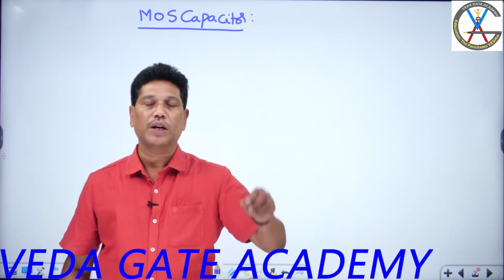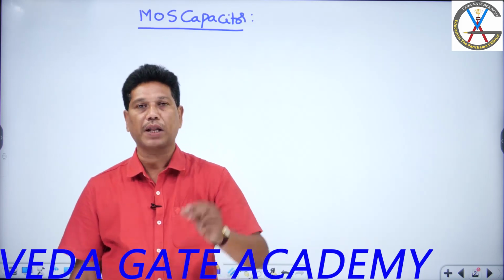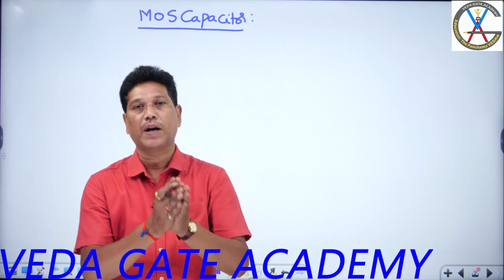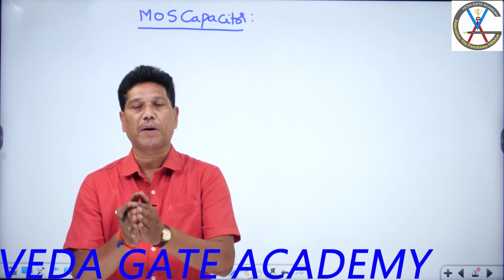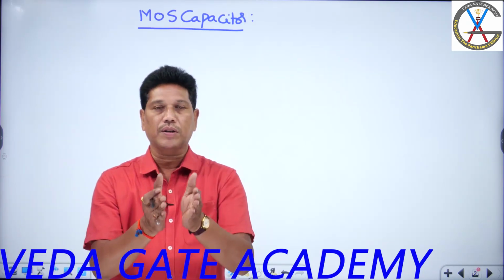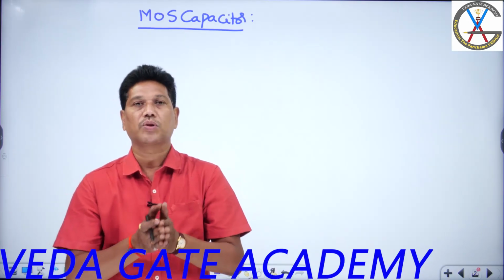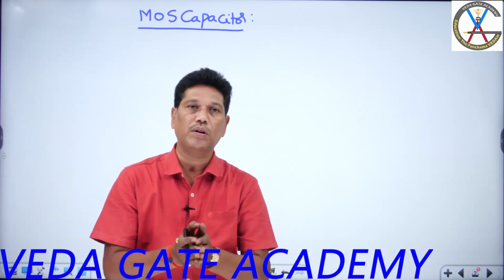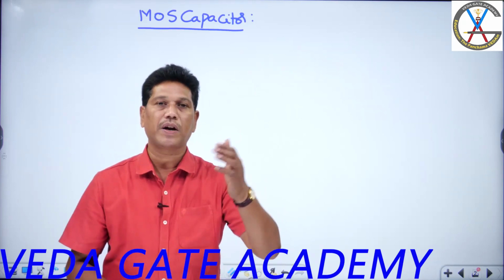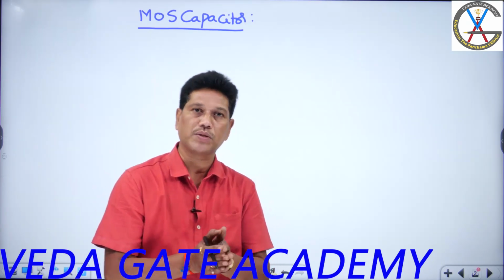And the capacitance of that MOS capacitor can be varied by the applied gate voltage, students. Based on that, this MOSFET is also called a voltage controlled capacitor or voltage variable capacitor. Confirm my option. In the case of MOSFET, there is a separation between the gate electrode and the conducting channel by the oxide layer of SiO2. That structure looks like a capacitor called a MOS capacitor, and that body capacitance changes with the applied gate voltage. Based on that, the MOSFET can also be called a voltage controlled or voltage variable capacitor, students.